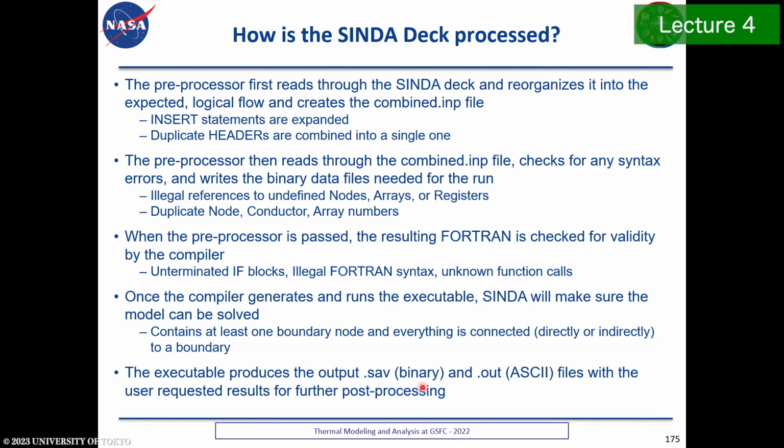So when you look at your Cinda input files that Thermal Desktop generates, there's a few headers there, and there's usually the operations block, and then it inserts the CC file, which has all of the node data, conductances, heat loads, contactors, conductors. And it will next insert the radiative files that you've defined. So if you defined a rad-k for internal, another rad-k for internal, then an external rad-k, and then the heat rate files, those will be 2 files. There's an HRA and an HRL. And then any other files that you might have inserted.